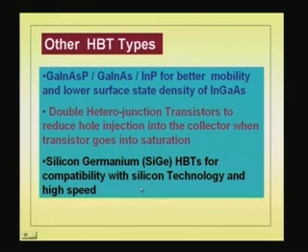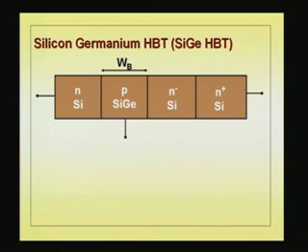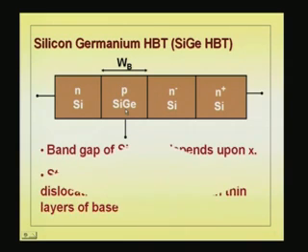In fact, IBM has been working on it, and it has succeeded in doing this combination of silicon germanium transistors and CMOS, BiCMOS. Let us go through that and see why and how this gives better performance, or comparable to that of compound semiconductors like gallium arsenide based devices. That is the structure: silicon emitter, silicon germanium p type, silicon n minus, silicon n plus. You will be wondering, you are putting a lower band gap material, but that is the whole key thing here. Let us go through this quickly and see what other benefits you get.